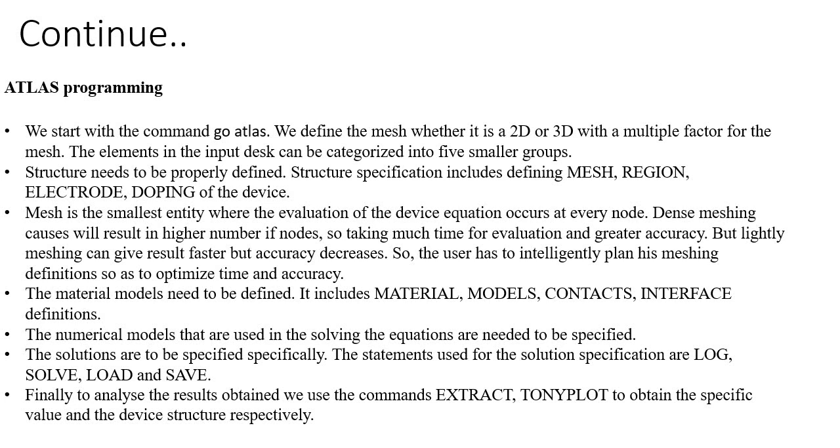The next section is the material section, where you have to define materials, models, contacts, and interface definitions also. The numerical models that are used in solving the equations need to be specified. The solutions are to be specified. Specifically, the statements used for the solution specifications are log, solve, load, and save. Finally, you can easily extract the structure in TonyPlot in 3D or 2D schematics.